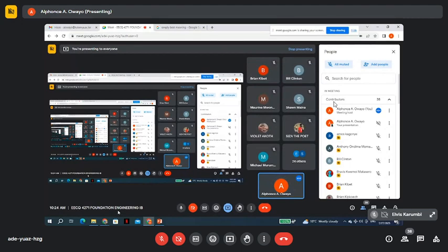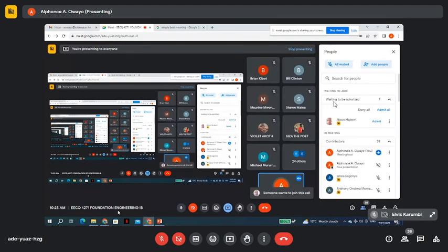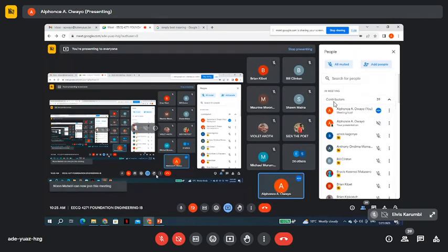Okay, so now from pad footing to combined footing, raft footing, you can reinforce them with some beam. So those are shallow foundations. Then if that is not enough, you can go to raft or mat footing, where it's a whole pad. Okay, if that is not enough, and you had problems of settlement, then you go to piles. Piles and piers, which now you should know how to deal with. But then if that is not enough, then you can have a group of piles.